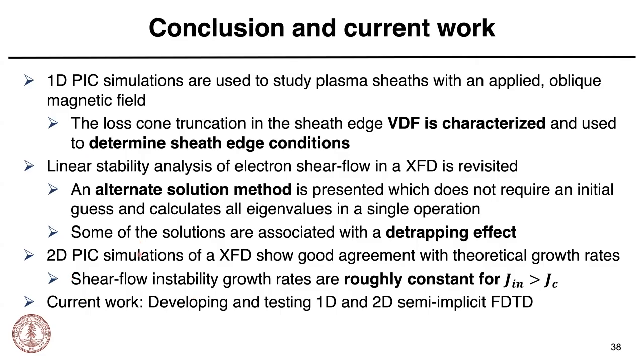Okay, yeah, that's a great question. With the 1D PIC simulations, they're of course much simpler. They wouldn't take too long. These were parallelized using particle decomposition, and like I said, we'd have around 35 Debye lengths for that simulation domain, and everything is in normalized parameters. We would have around 10 cells per Debye length, so pretty well resolved, and around 3,000 particles per cell. We can get away with that because it's 1D, and we want really nicely resolved VDFs. That's why we have a lot of particles per cell.